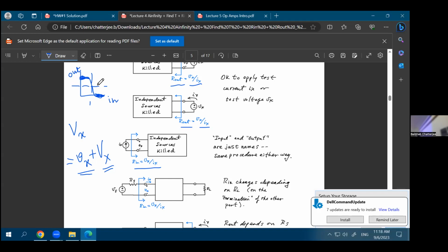Question? So in that case, you just basically apply a DC offset. Exactly. So you apply again a DC offset, which is an average of these two. Apply maybe 2.5, so apply somewhere over here instead of applying at 0. So have a DC potential of around 2.5 volt. Apply your AC potential, and you'll see a large swing at the output. Okay, so that's the meaning of bias. That you apply a DC bias so that you can expect gain.